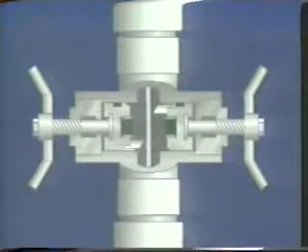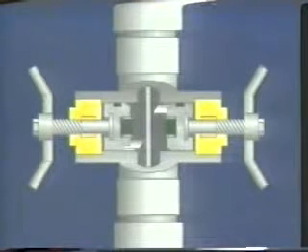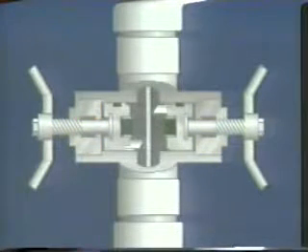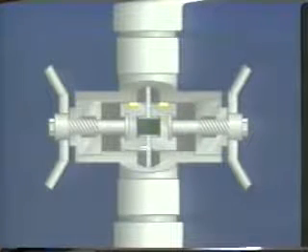Anytime wire line is run into a well, there is always the possibility that something could happen that would require the well to be shut in while the wire is still in the well. The wireline valve permits the specialist to do this without damaging the wire line. The wireline valve consists of a body, a set of opposing rams, ram stems, ram caps, and an equalizing assembly. The ram assemblies have rubber seals which seal around the wire line to contain the well pressure. The rams also seal in the body of the wireline valve to prevent well pressure from escaping around the ram when the valve is in the closed position.